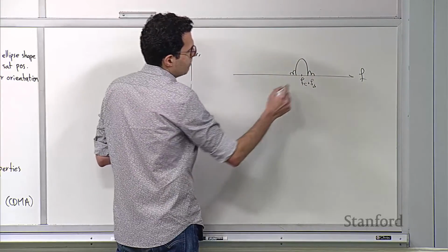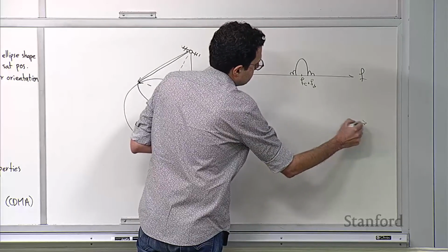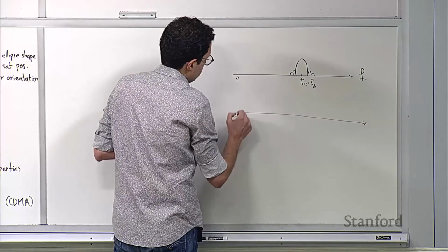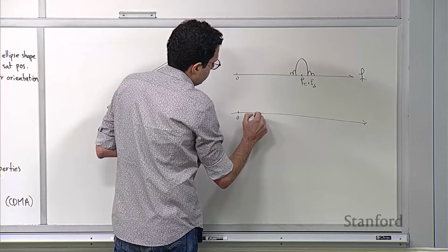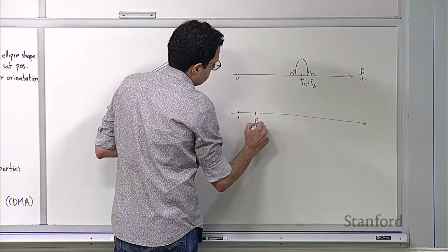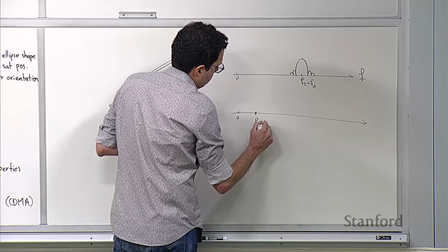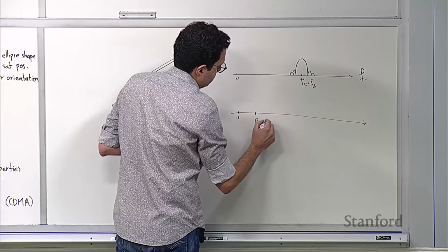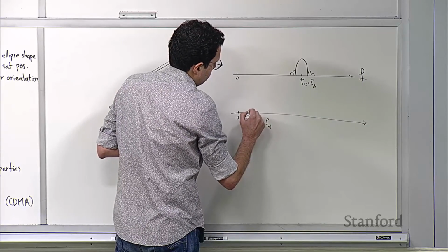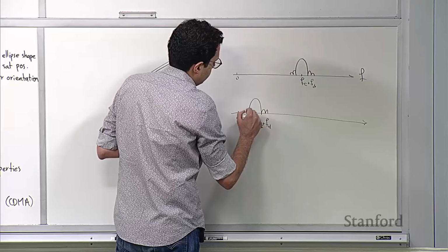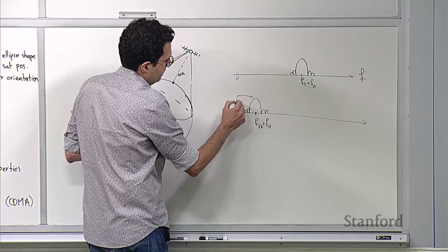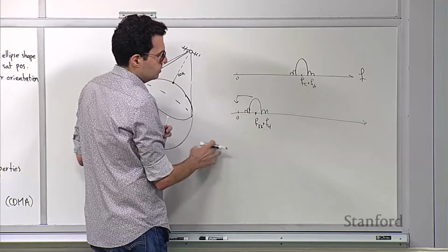And the first step brings this down, and let's say this is 0, brings us down to some intermediate frequency. Still, we have the f_D offset, right? So you come here. And then later in DSP, you bring it further down, as we'll see, to baseband, and then you do your correlation.